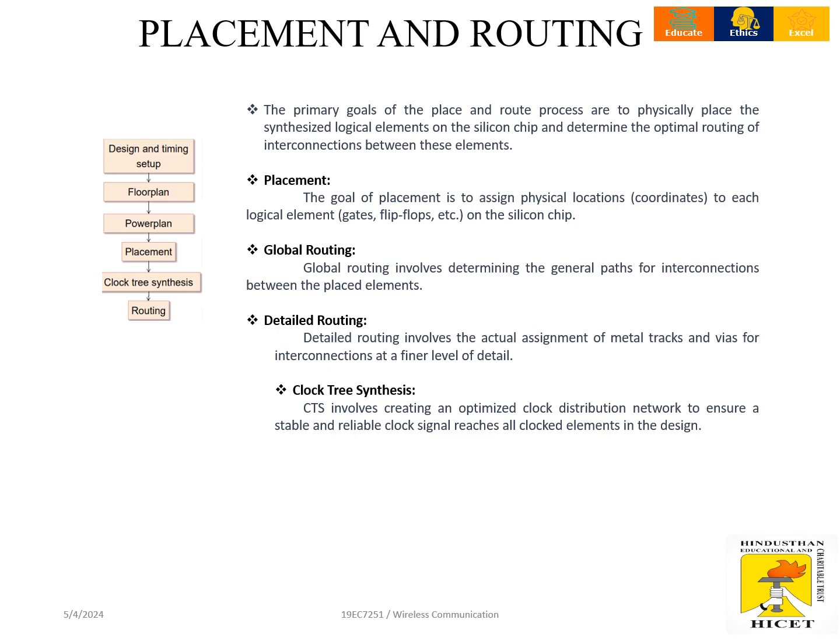And next is the backend, that is the placement and routing. The first process is placement, and here in this placement, the global placement is to assign the specified location, and in detailed placement we have to do all the things. And next is the routing, and in routing we have two different steps. One is global routing, another one is detailed routing.